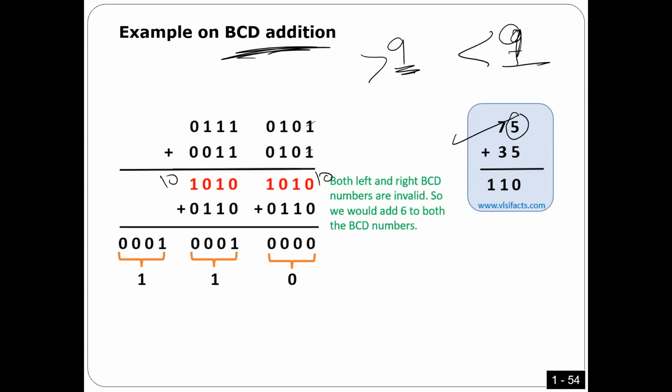So now, after you finish, you need to do the adjustment, okay? Because you added in binary, you just need to keep this number here between 0 and 9. For the adjustment, if the number here is greater than 9, you have to add 6 this way. If the number here is less than 9, you just add zeros. Okay, and then you do another binary addition here.